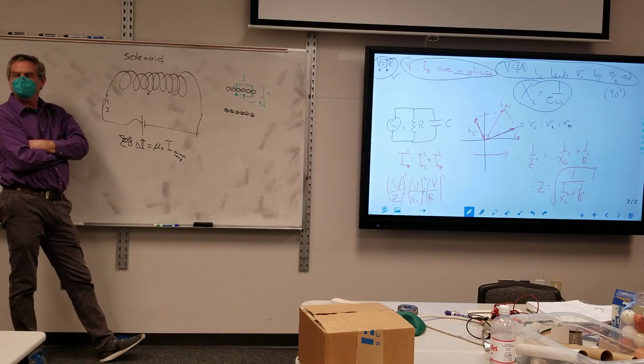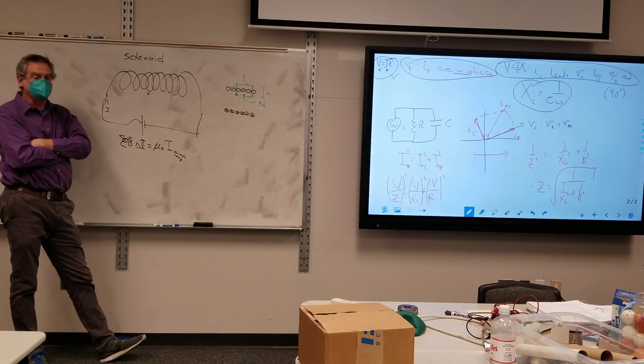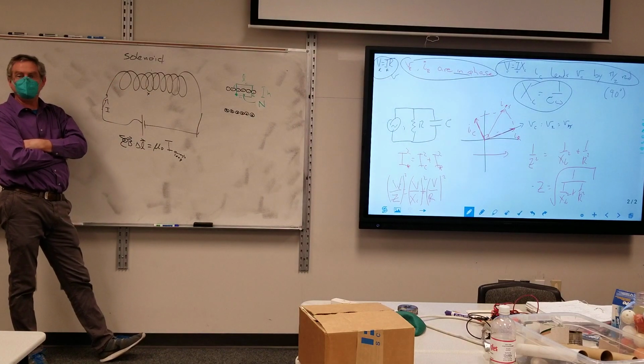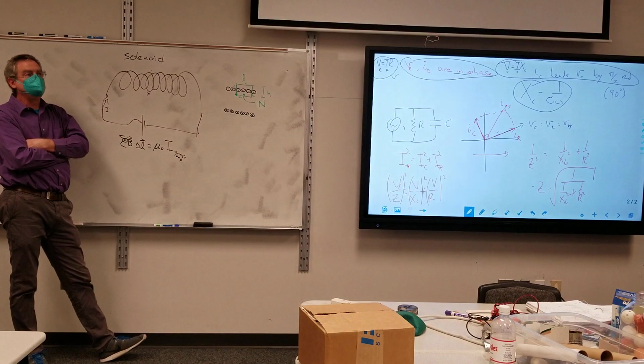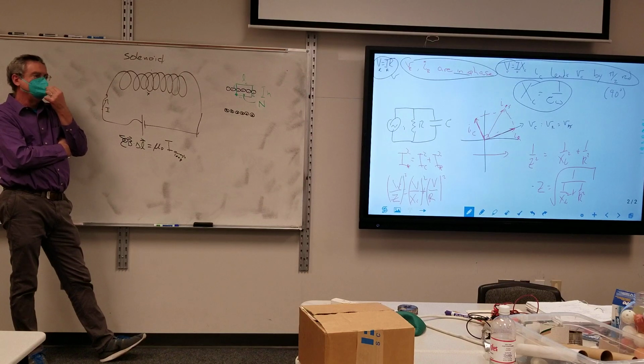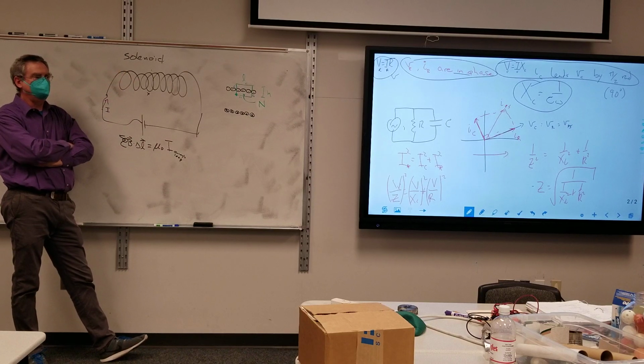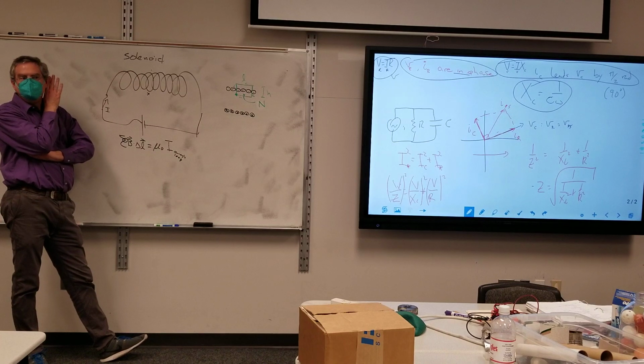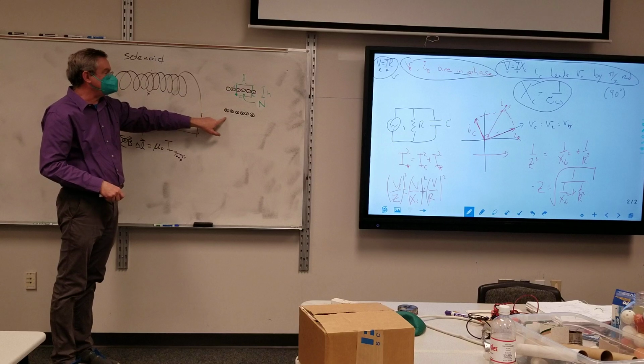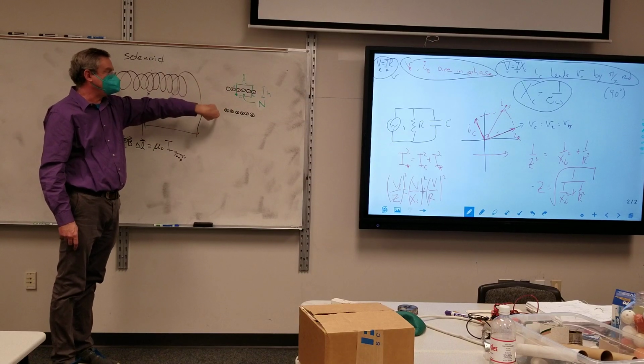Is it just one before? In terms of I, how much current's flowing? Piercing the loop, going through the middle of the loop. Half of I? Why half? Because half is going this way, the other half is going the other way. If we think about current, when current's flowing through it, I is going through every wire. So it would not be half of I. It'll stay the same. Whatever current's flowing through here is also flowing through that, just that's going this way, that's going that way.